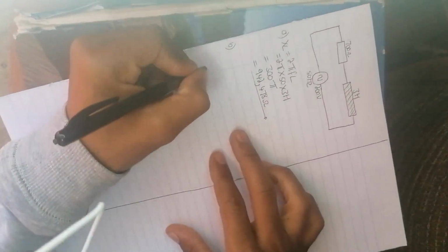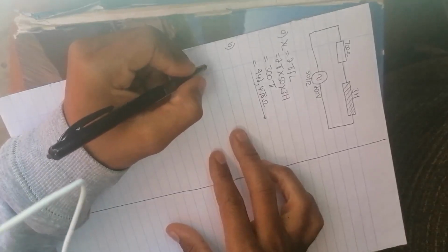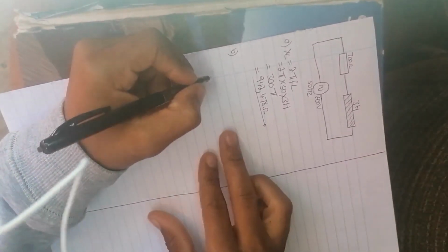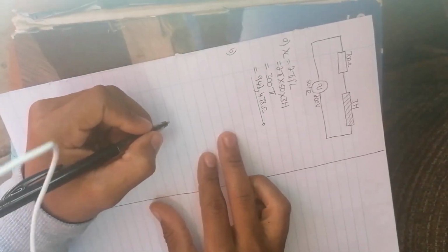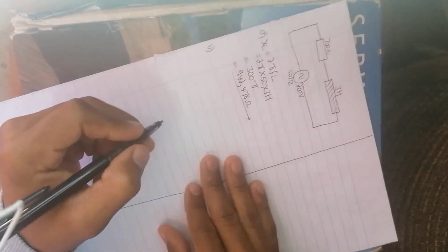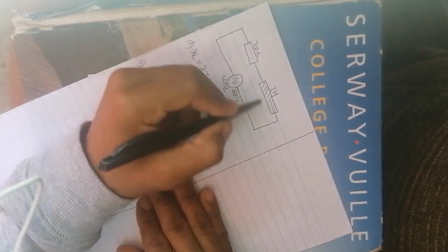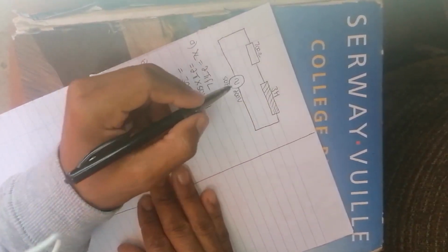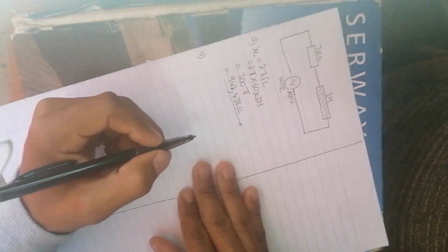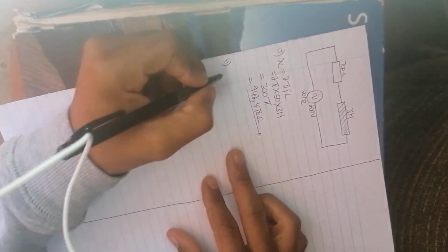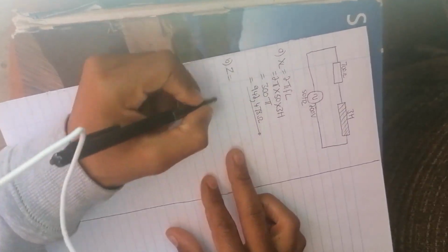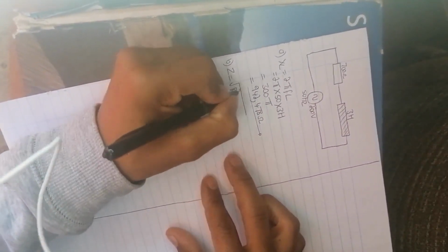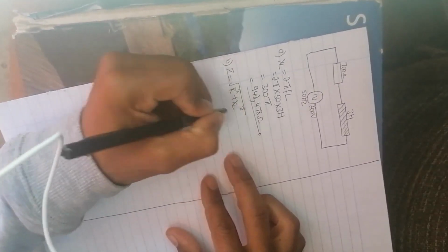We go to number B, the impedance of the coil. This is what they are looking for. I know that the impedance of the coil is the total resistance of the circuit. And then via the phasor diagrams, I saw that the impedance is found using the theorem of Pythagoras. So that is to say, Z, which is the total resistance of the circuit, is the square root of R squared plus XL squared.